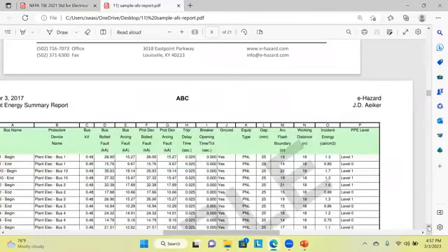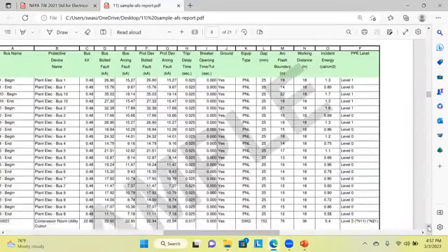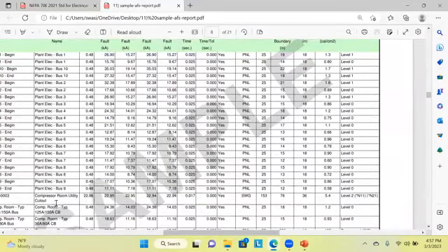It could be like, for the 22 kV system, 36 inches, and the restricted approach boundary and the limited approach boundary will be based on the voltage level. So this boundary can come in between the limited approach boundary and restricted approach boundary as well.